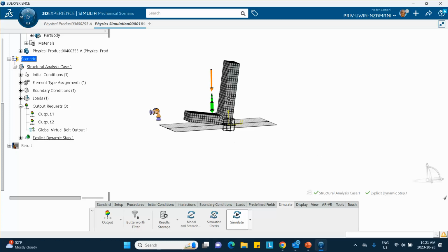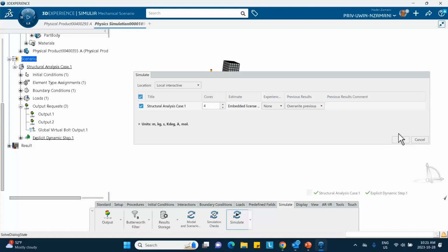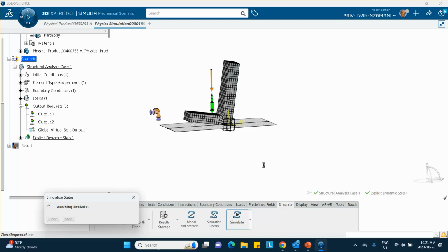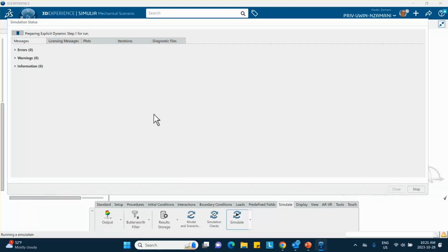Hopefully, we're going to get to see the ball, this thing hitting the ground and then bouncing back and forth, etc. If not, we're going to have to change our duration slightly, make it longer. Because I noticed that there was a bit of a gap there, and in that gap, nothing happened. It's just that the L-shaped region is going to come down and hit the analytical surface, so we don't gain anything.